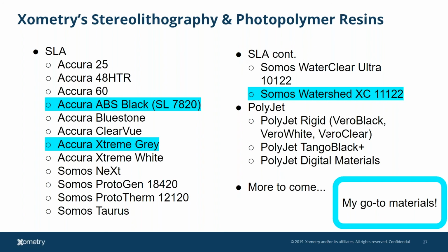The reason why I wouldn't say a PolyJet clear, the clear material is actually great, but there's a support material over it, and when you have something like a syringe, sometimes cleaning out that support in those channels and features can actually lead to some cosmetic marring on the parts. So I'd point you probably towards the polycarbonate-like clear materials like Watershed, which will bring you in the right direction, or Accura 60.